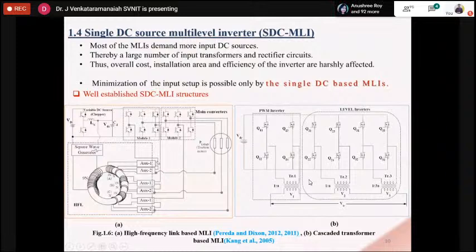At the output of each rectifier or auxiliary circuit, you will have a capacitor to nullify the DC ripple. These two DC values are connected to the H-bridge modules. We are using two modules, module 1 and module 2. In this module one auxiliary circuit is connected and another one is connected to the other. We can treat these two H-bridge modules for one phase, the next two for phase B, and the last two for phase C.